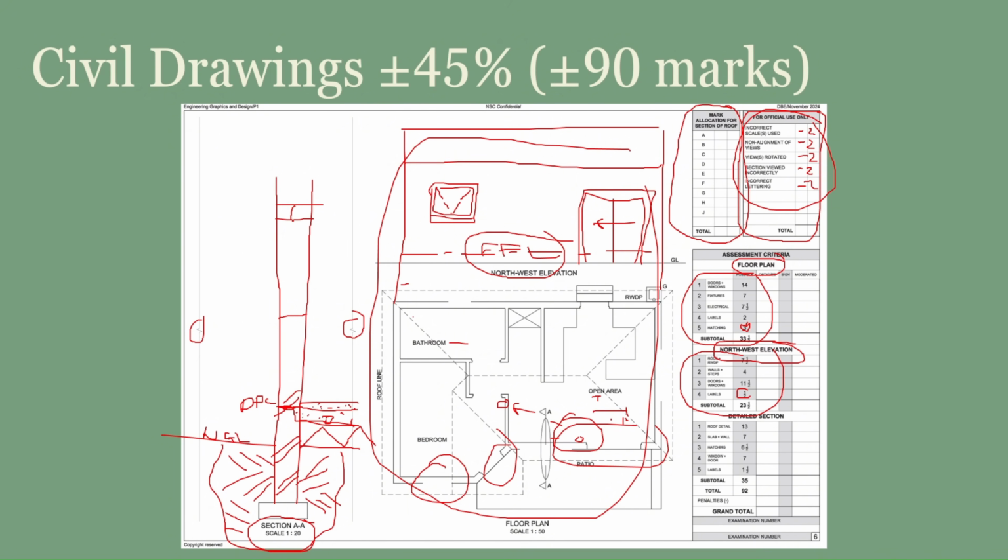Then we're going to have the window frame in the middle of the wall. Then there's going to be one brick, which is 75 usually, in a thickness down. You're going to add the windowsill in here at a certain degrees as specified in the question. Over here is also a DPC underneath the windowsill. We apply the hatching underneath the windowsill as just little dots for some cement. And the same here, some cement here, dots and a few triangles.